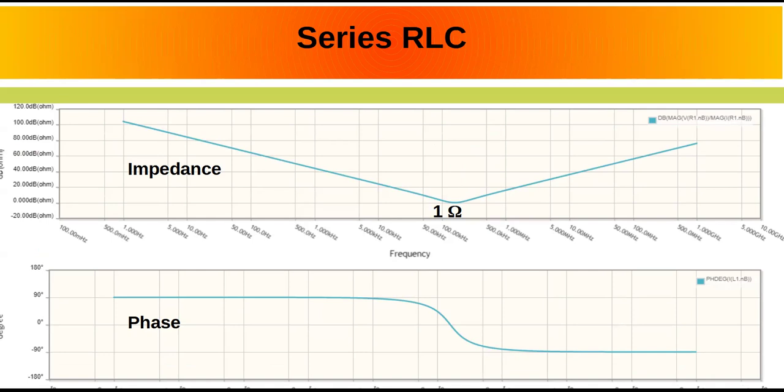The vertical scale label is dB ohms. And you use dB because the logarithmic scale of a dB with respect to an ohm gives you the linear chart as it goes left and right, upwards away from 1 ohm in the middle of that graph. Is that correct? Otherwise, it would be an exponential curve because of the squares.